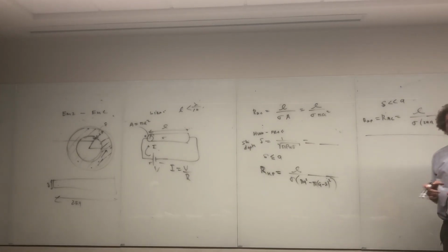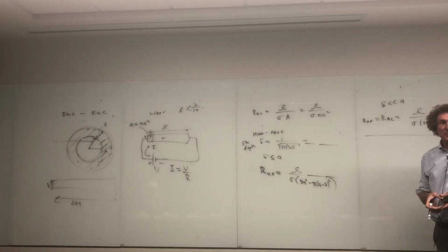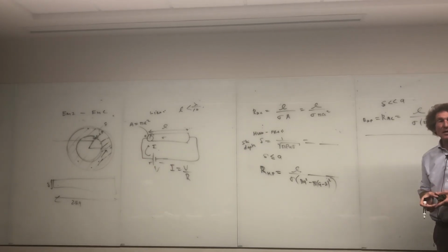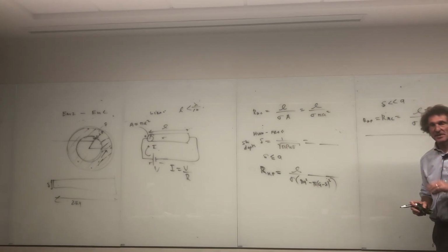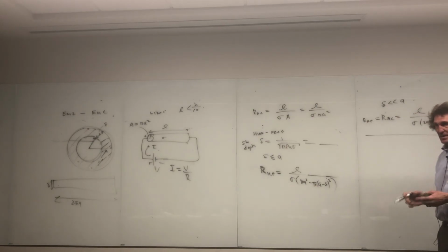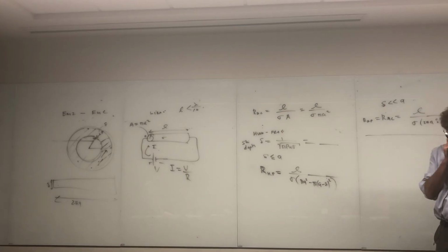All right, that's so much for resistance. The next thing you have to worry about with a wire is internal inductance. When you're modeling anything at high frequency, inductance becomes a nuisance. You would like zero inductance, but you can't have that. I can speak from personal experience: I've had more trouble getting rid of inductance than any other thing in high frequency engineering. It is an absolute pain, because the only way to get rid of it is to make your leads of zero length, and you can't do that. So you have to work around it as best you can.